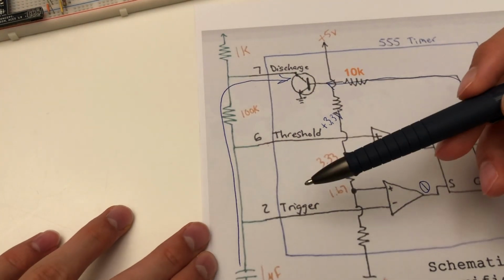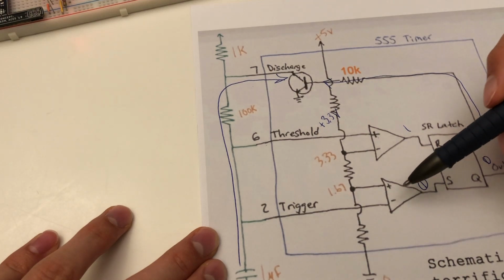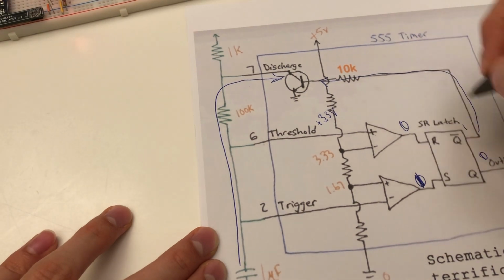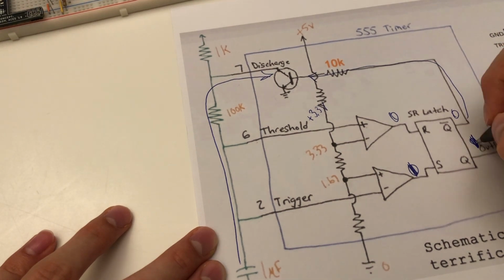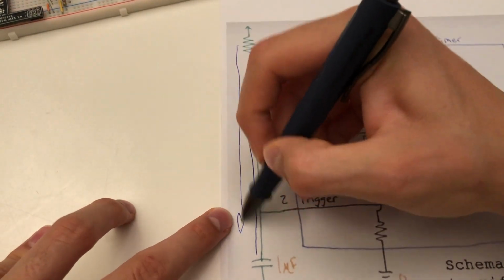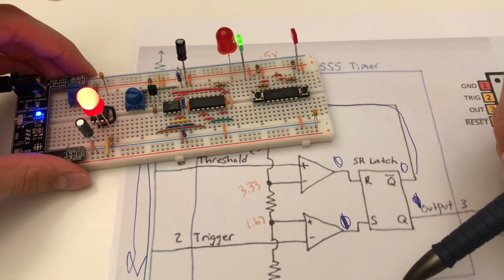When C1 drains to 1/3 of the source voltage, pin 2 carries the signal to the inverting input of the second comparator, which sets the latch. That means reset would also become low. Q0 becomes low, and the output is high once again. So that closes off the transistor, and now the capacitor starts to fill again. This whole system repeats itself, and that is what causes the oscillation.